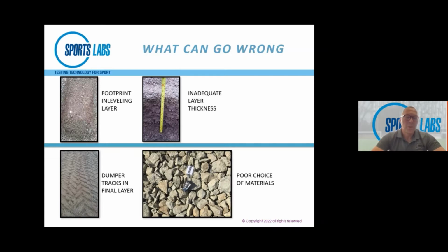So the materials itself, the slide there with the very, very uniform big stone, very difficult to level and very difficult to compact. So it's a very mobile material. It causes all sorts of problems when you're trying to lay turf over it because it moves around. You pull stones up, and it's just not a good material to try and finish the subbase off with.